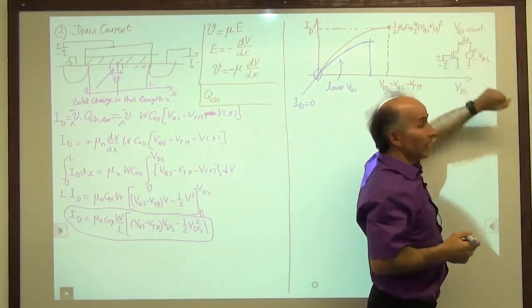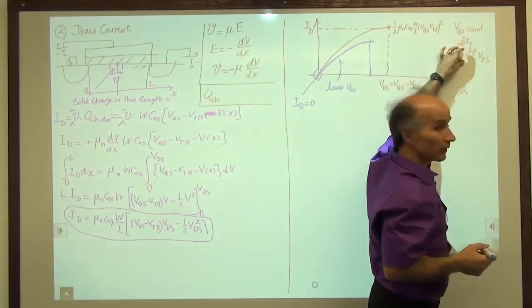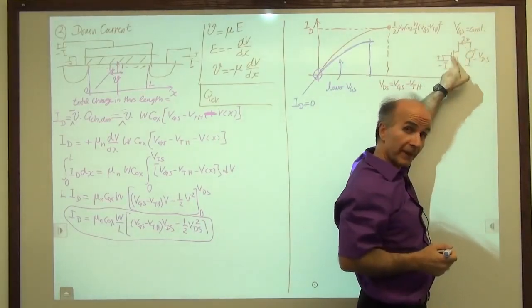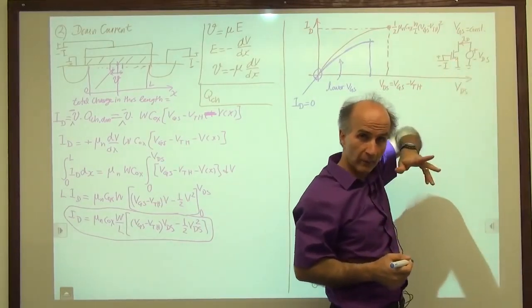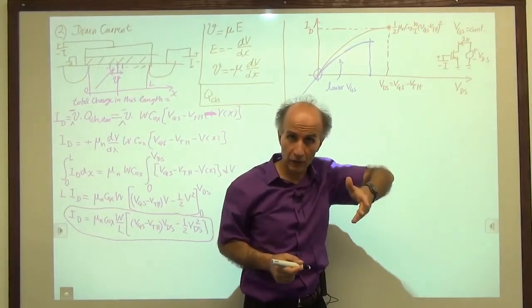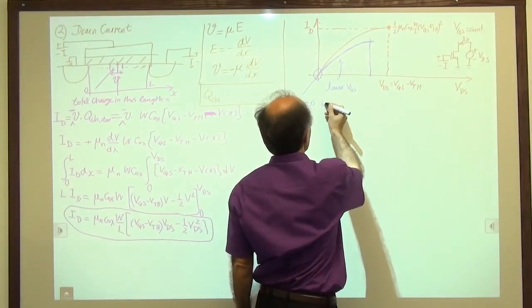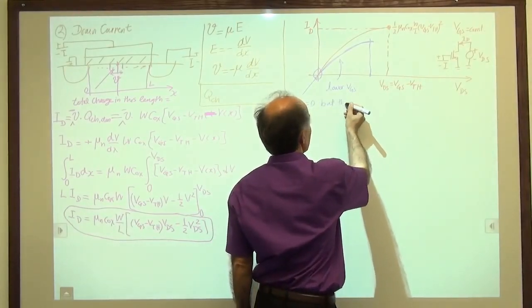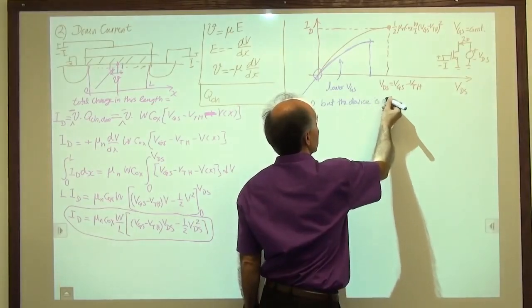The gate voltage is some amount. So around here, VDS is 0. This voltage is 0. We have no current going this way, but there is a channel inside the device. So as I said, this is a unique property of MOS devices. They can be on, they can have a channel of electrons, but they have no current. So ID is 0, but the device is on.